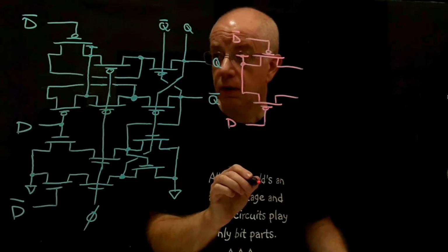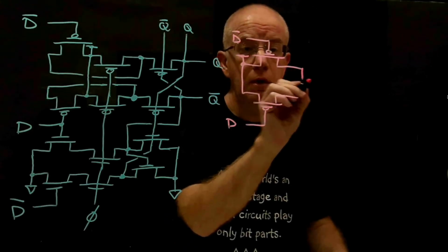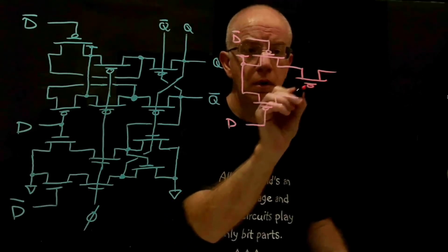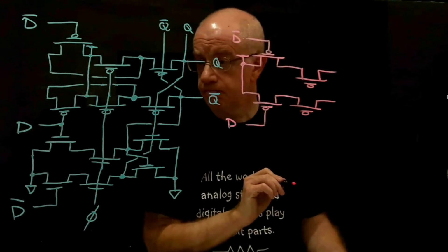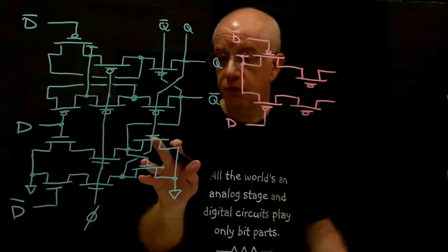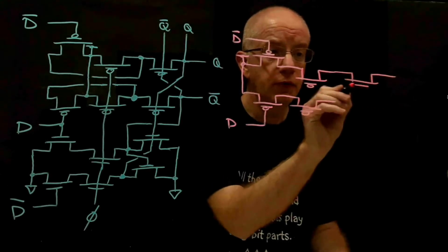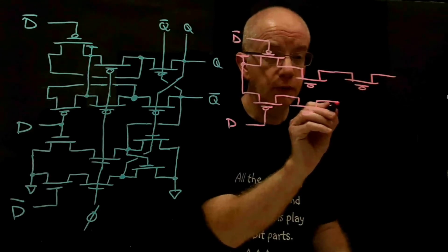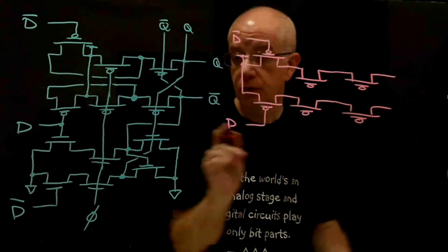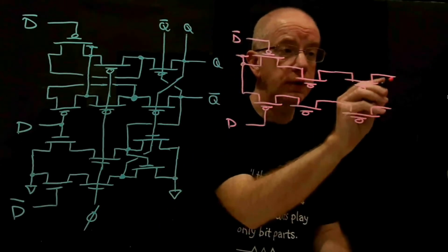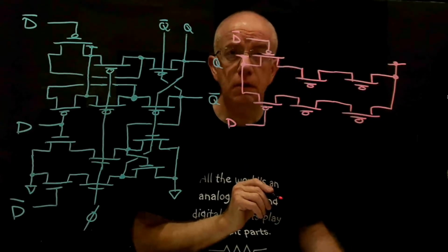And now, let's see, we have these 2 transistors, 2 clock transistors, like so. Then we're going to have 2 PMOS transistors for the cross-coupled inverters. And those would be both facing, let's say, the same direction here. And this ground connection here will turn into a VDD tie up here, like so.